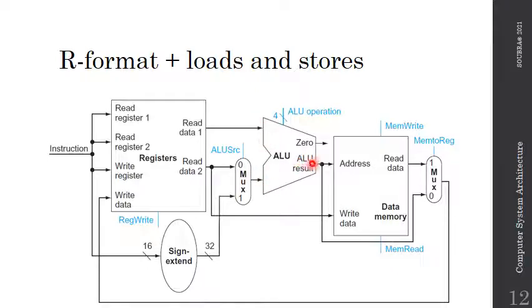And then the result that's happening here: in the case of an R format, you're going to see that I'm not going to go through the data memory. So for an R format, I come here and go back to the destination register that I need to write to. In case of a memory instruction, I'm going to use the read data that I'm loading and write it back to the destination register. In case of a store, I won't even be reading data, so it's already covered naturally.